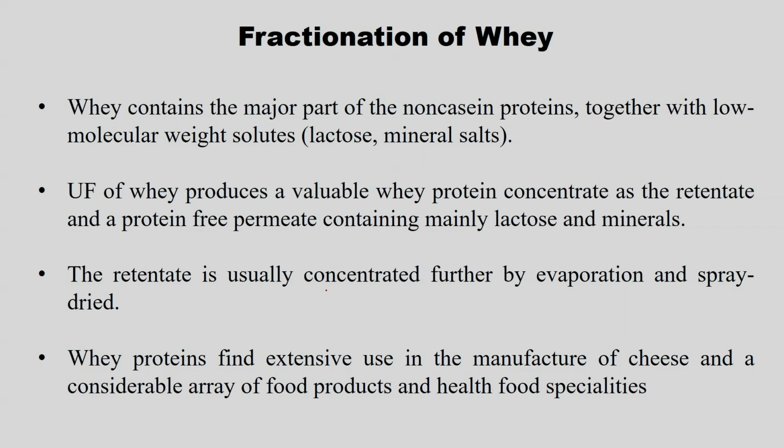The fractionation of whey is another application which is done using ultrafiltration. The whey contains the major part of the non-casein proteins, right. So, the curd is taken and it goes for further cheese making. For the removed whey, we further use a fractionation technique using an ultrafiltration membrane. Whey contains the major part of the non-casein proteins together with low molecular solutes, which include lactose as well as mineral salts. So, ultrafiltration of whey produces a valuable whey protein concentrate as the retentate and a protein free permeate containing mainly lactose as well as minerals.